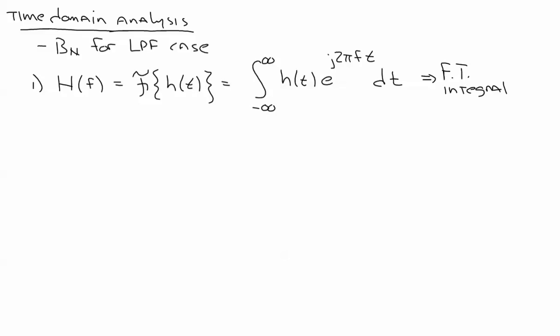Well, very quickly then, h of 0 is just the area of my impulse response. This is for a low-pass filter. I'm assuming a low-pass filter here, folks. H sub 0, which is my transfer function evaluated at 0, is the area under my impulse response.